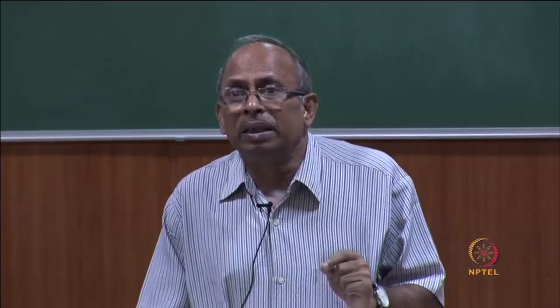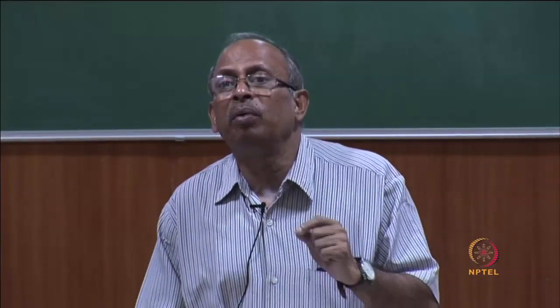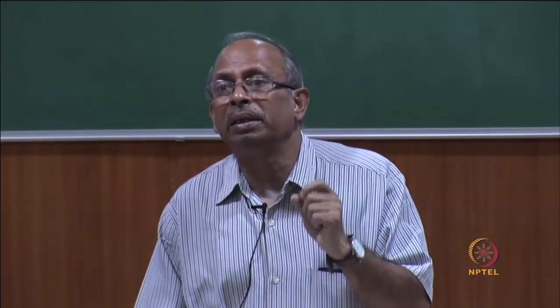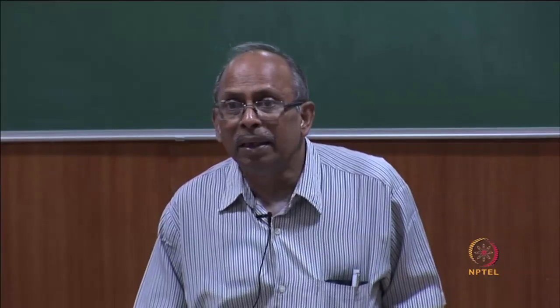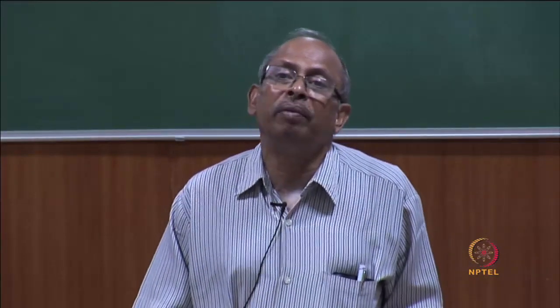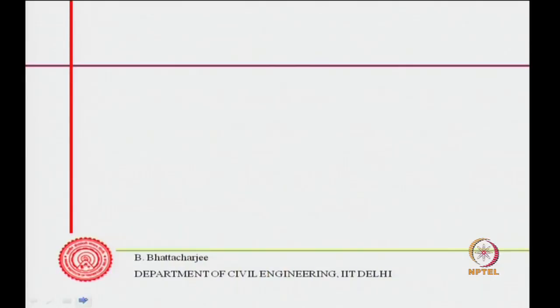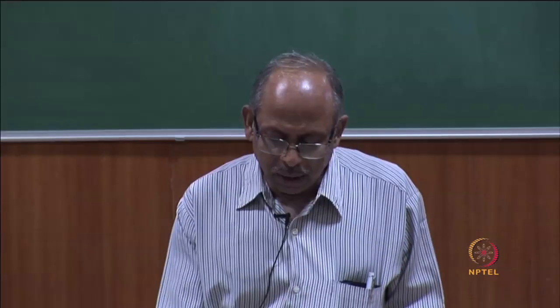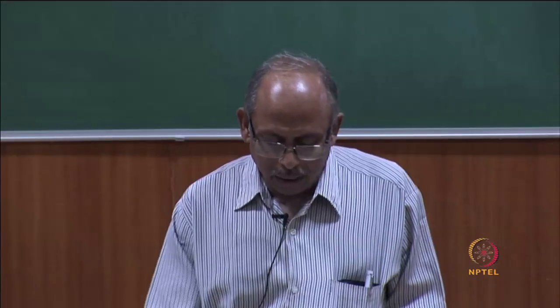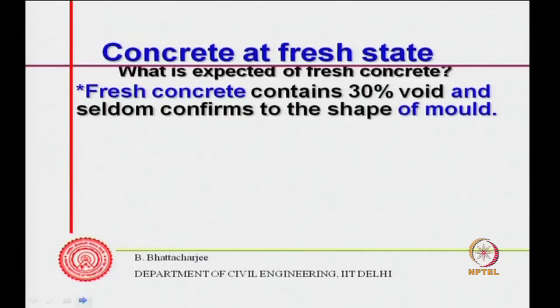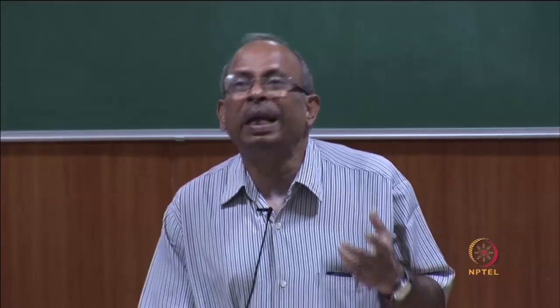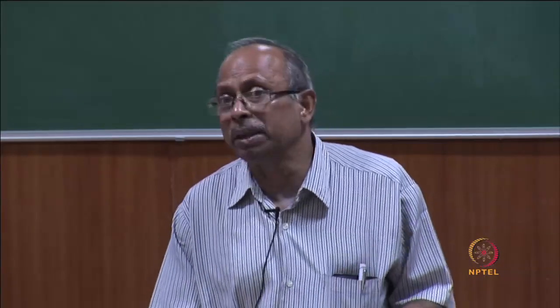So, it means that minimum paste content must account for the above void content, that is 1 minus dP max, and more to account for wall effect and loosening effect. So, 3 to 10% more, that is, dispersion is 3 to 10%. So, what you can do is you can take about 10% more void, you can take about 10% more paste.